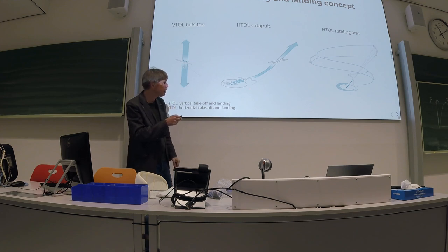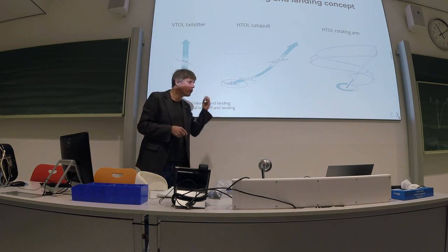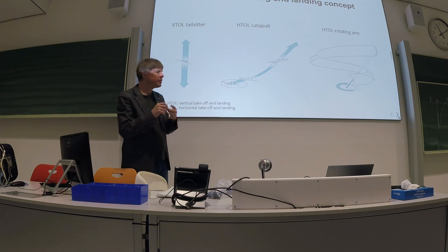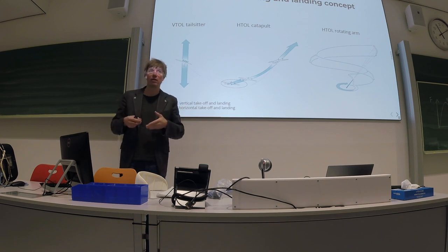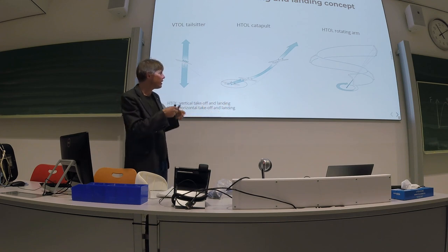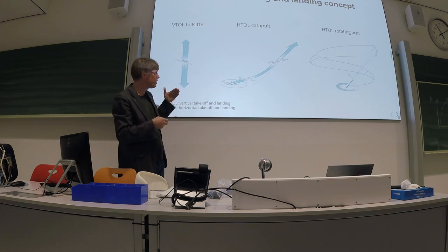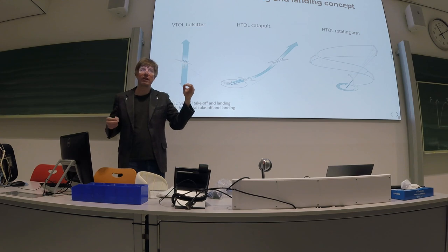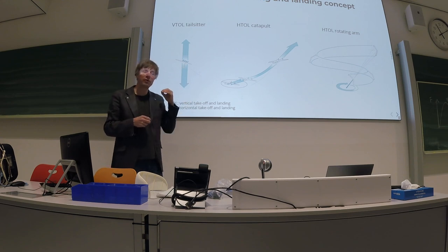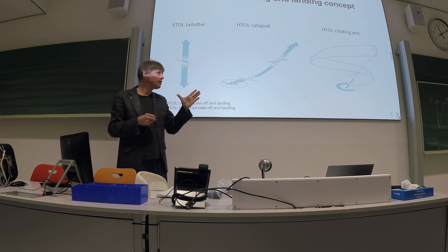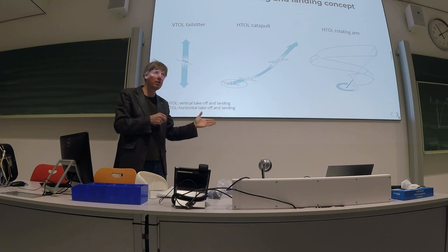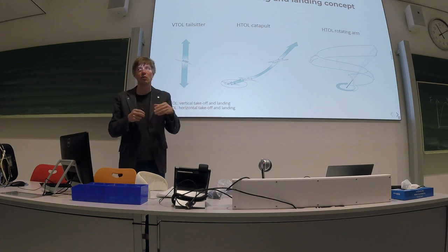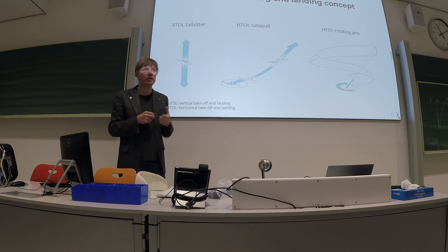It's tethered, so there you can already imagine here that there will be a transition phase where you go from launch, where the tether is slack and just fed out, into a phase where the kite flies crosswind maneuvers and the tether is highly tensioned. And you can already imagine that the transition from the one mode, takeoff, to energy production is critical.